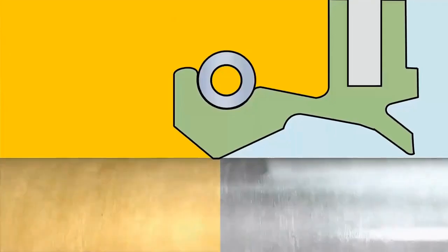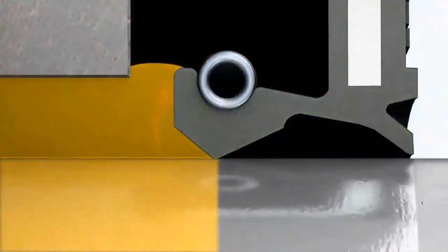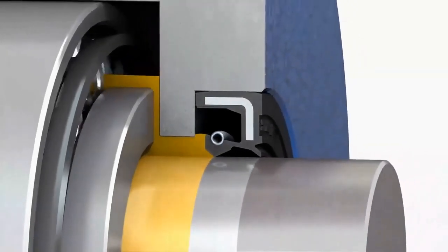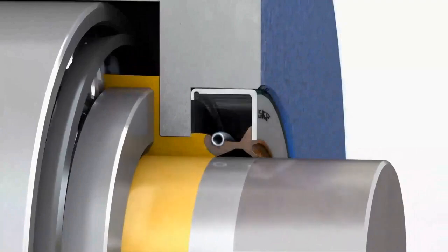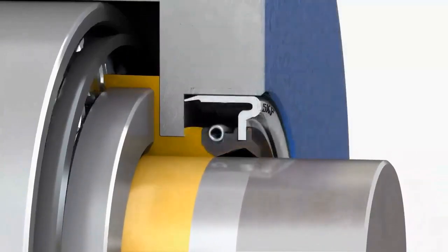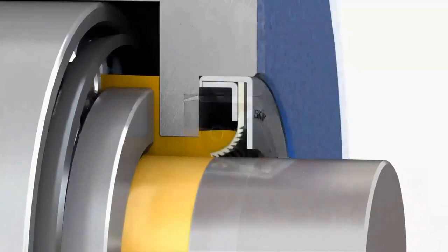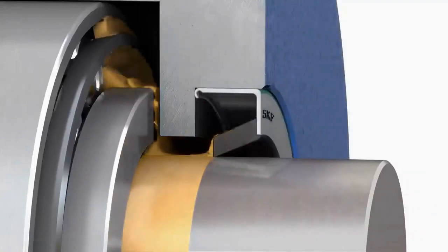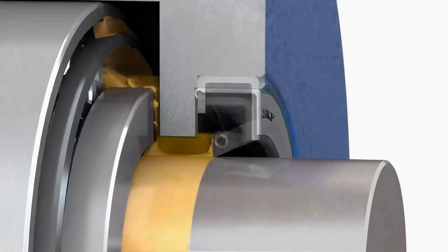In its application, seals have different materials and cross-sectional shapes to suit different operating parameters such as the type and pressure of the fluid in the engine, shaft rotational speed, working temperature, shape and dimensions of the seal housing, as well as external environmental conditions where the machine will be operated such as weather, humidity, temperature, outside air pressure, corrosivity, immersed in water, immersed in mud, flammable gas area and so on.